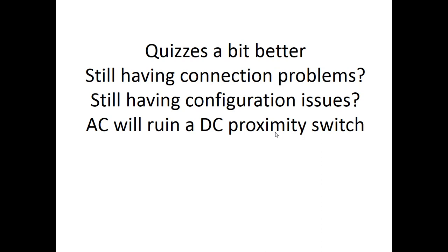Still having configuration issues? You should be able to make RSLinx connections and then start your program and configure it. Some people were having problems with this because they were doing their program and addressing, and then they were getting errors because there were no input or output cards installed or configured, and they just typed the inputs instead of dragging them, and they weren't there.